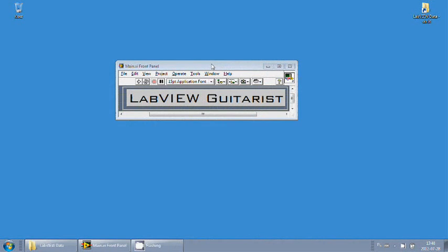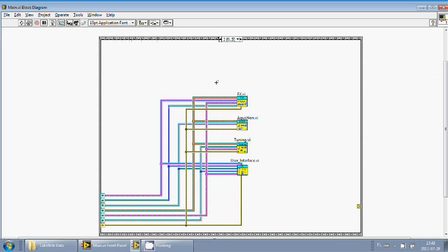The application was built on four threads connected with each other with queues and notifiers. There are acquisition, tuner, processing and user interface threads. The user interface collects data from the user and, basing on it, sends commands and information to the front panel and other functions. The acquisition thread receives data from input and sends it to the currently working thread, record or tuner or any other.